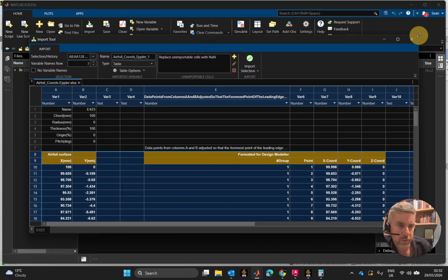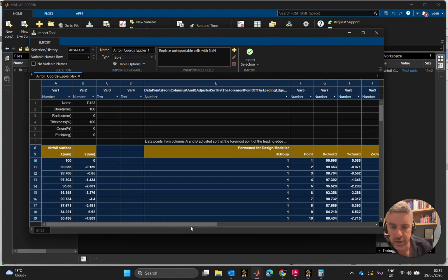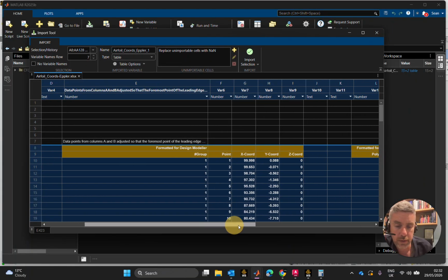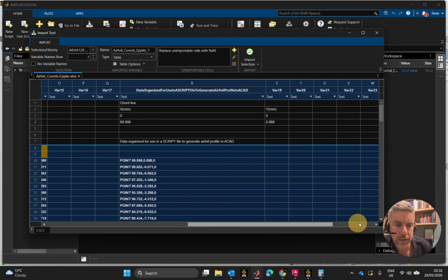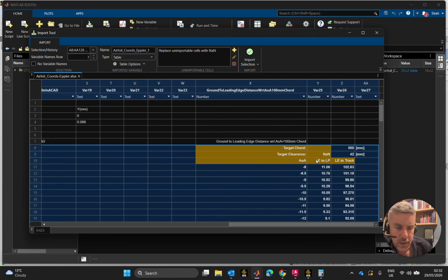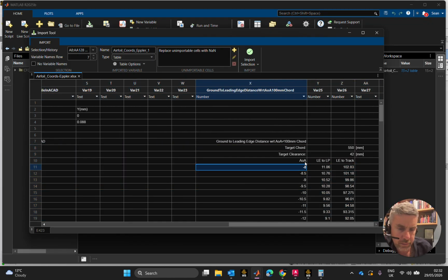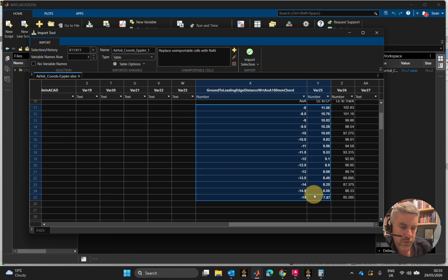So a little bit of curve fitting. We're either going to run with possibly a second order polynomial, an exponential function or a power law. I doubt a linear will help us any. And this is the data I want to bring in: my angle of attack and my leading edge to low point height. So this is the dependent variable, and this is the independent variable. Let me scoot in these two pieces of data. Let's import, and that'll write a variable.